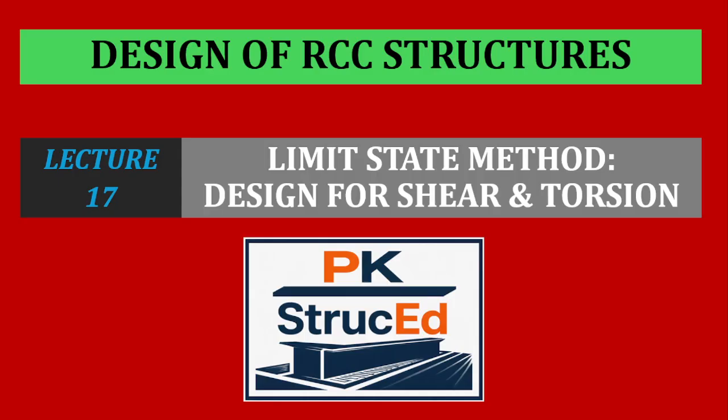If shear and torsion are not properly designed, a sudden brittle failure may occur, wherein the structure may fail without warning even if flexural design is safe. Now, why is this topic important? Flexural failure is ductile and gradually taking place, whereas shear and torsion failures are sudden and catastrophic. Therefore, shear and torsion design governs the safety.